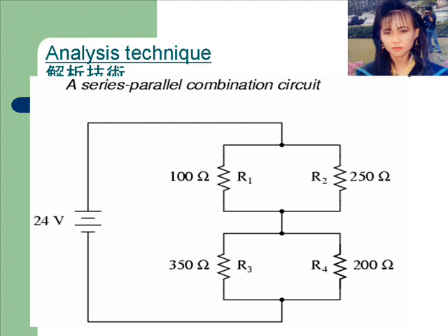Step 5: Taking total voltage and total current values, go back to the last step in the circuit reduction process and insert those values where applicable. Step 6: From known resistances and total voltage and total current values from Step 5, use Ohm's law to calculate unknown values of voltage or current, I = V/R.